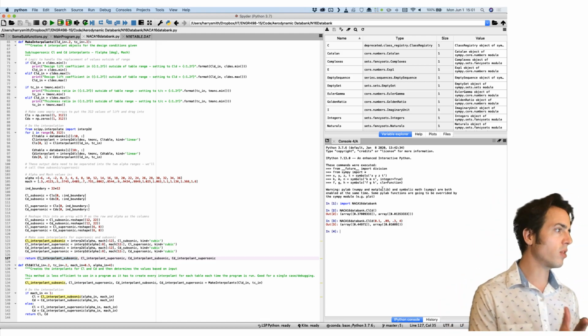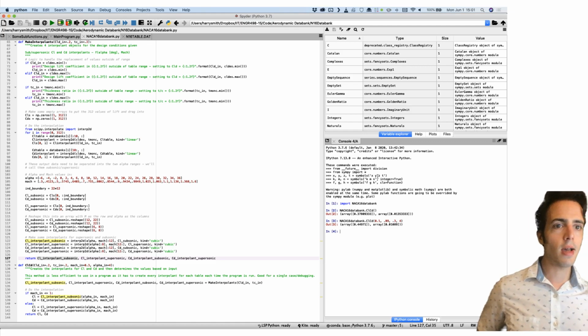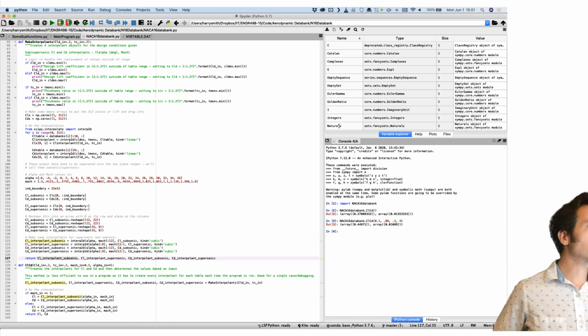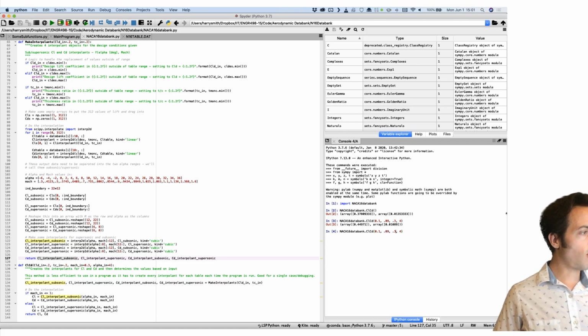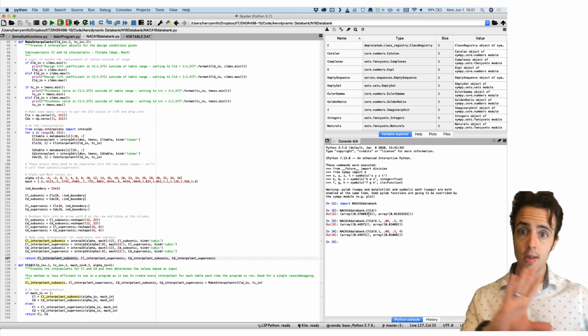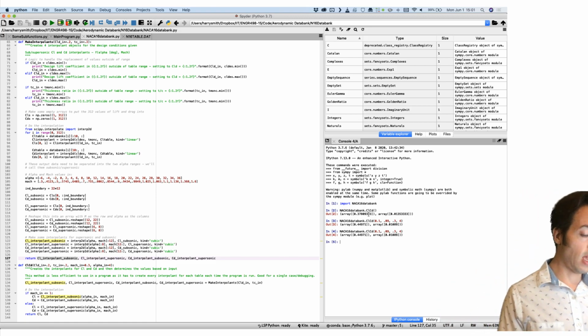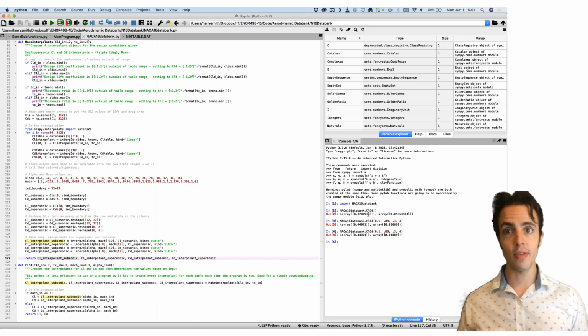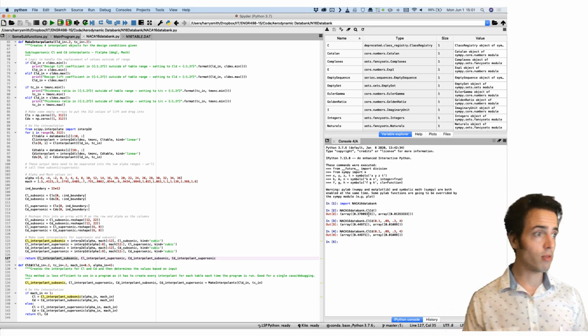because importantly, what we've got now is, if I look over in my Spyder command window, you can see what I've written here. So NACA 16 Databank, I can immediately see for a design lift coefficient of 0.1, for a thickness chord ratio of 9%, travelling at Mach 0.3 and alpha of 4, these are what my lift and what my drag are, according to the Databank. So we could use that in our experimental code when we look at the performance of propellers. It's going to be really useful.